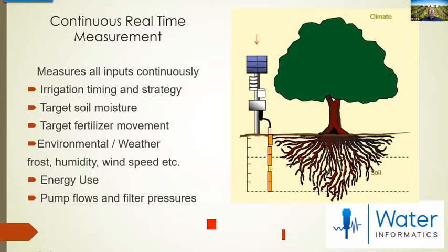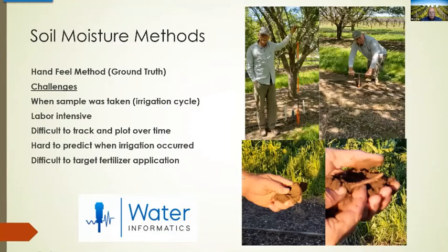So if you called for a 10-hour irrigation due to ET and your filters are flushing every hour, you may be only putting 9 hours on. Understanding and seeing that data come back to you on what those filters are doing and how often they flush is super critical on how we run our irrigation systems.